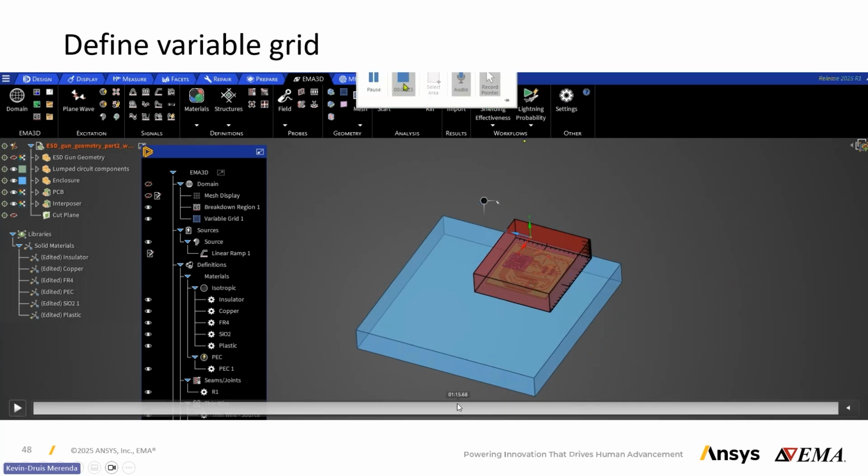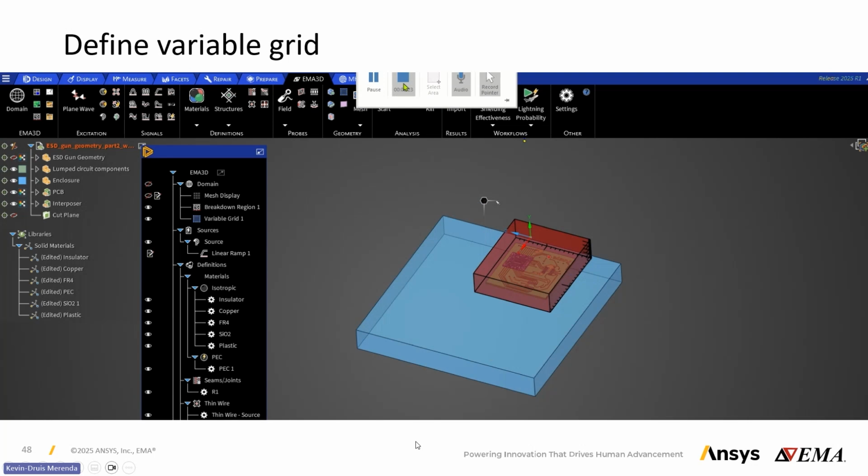One thing to note is that the FDTD needs to have a conformal mesh, and by that I mean that you can't have staggered cells. Each of the mesh elements needs to be connected at their corners or vertices. This makes it so that the grid has to be very fine all the way through the whole domain.